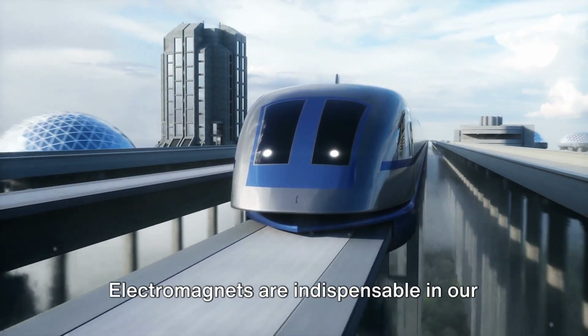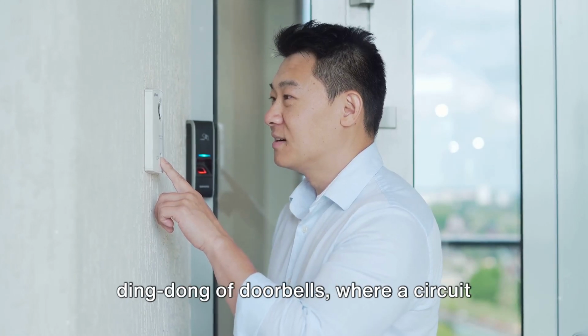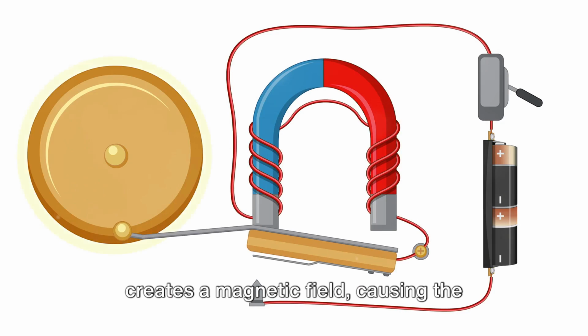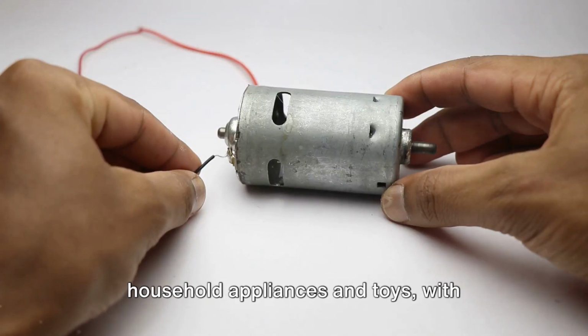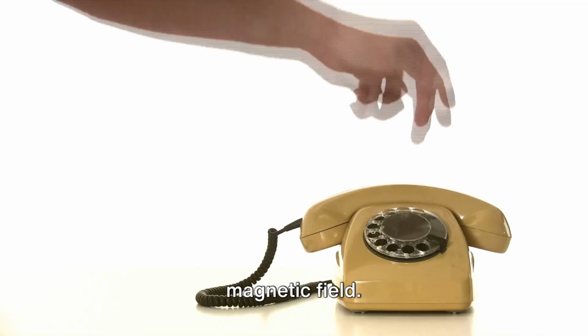Electromagnets are indispensable in our modern lives. They're the driving force behind the ding-dong of doorbells, where a circuit with an iron bar and a small hammer creates a magnetic field, causing the hammer to strike the bell. They're central to DC motors, powering household appliances and toys, with current-carrying coils rotating in a magnetic field.